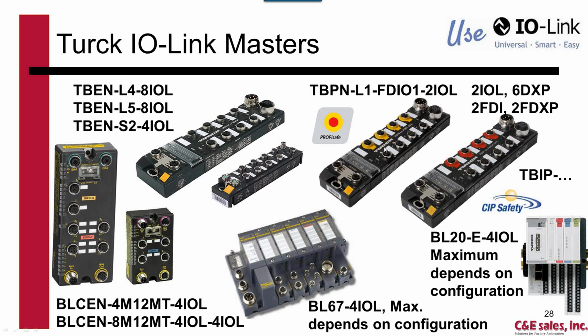And then we have the hybrid modules. There's one for PROFINET where you can do IO-Link, standard IO, and safety IO in one module. And then we also have the one here for CIP Safety for use with an Allen-Bradley safety PLC. So we have the safety IO, IO-Link ports, and standard IO. Those are the hybrid modules.